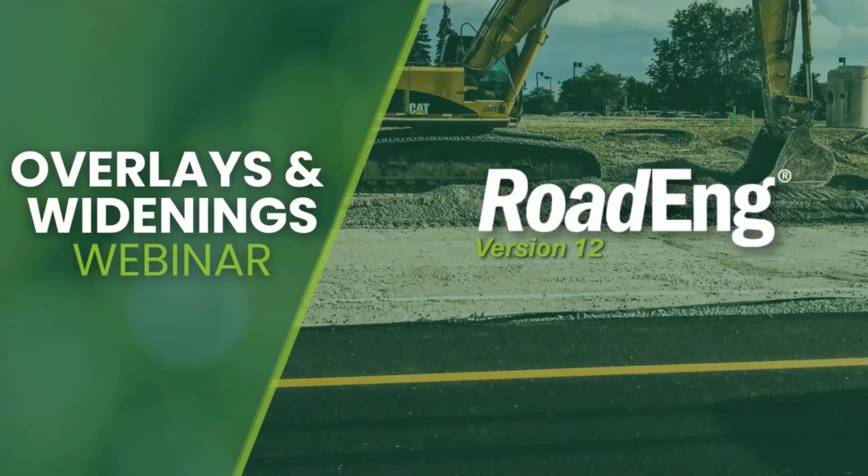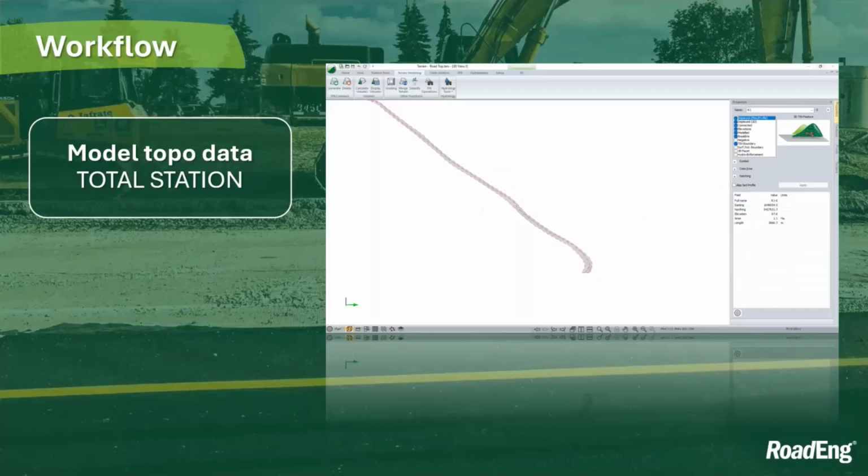Beyond that, let's take a quick look at the workflow for today's presentation and topic. To start, the very first piece of our workflow is modeling our topo data. For this, we're going to be using conventional survey data as well as DEM data. In the very first step, we're going to import and model that total station data. Specifically, we're going to bring in data for the center line and road edges of that existing road that we're looking to do our widening and overlay project on.